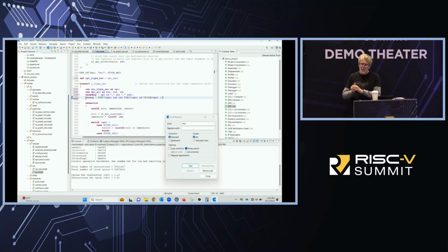And instead of just using RD, I'm going to say RDRS3, so you can see that it means both. It's not just RD, it's not just source, but it's actually going to be both a source and a destination. So I have to come to the binary and say the same thing so that it matches up there. So I'm getting pretty close to finishing my ISA model by adding a new resource and a completely different type of instruction.